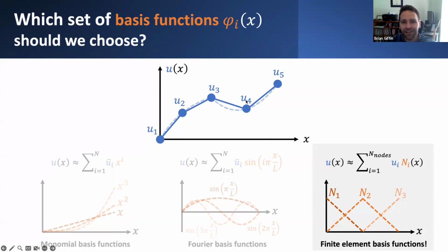And they also constitute an interpolation. These basis functions allow you to represent the solution as basically being equal to these different discrete values at these discrete locations of interest. And in between each of these discrete locations, we interpolate the solution field in a simple way, such that we assume that maybe in this case, the solution varies linearly between these two discrete values where we're specifying these corresponding coefficients.